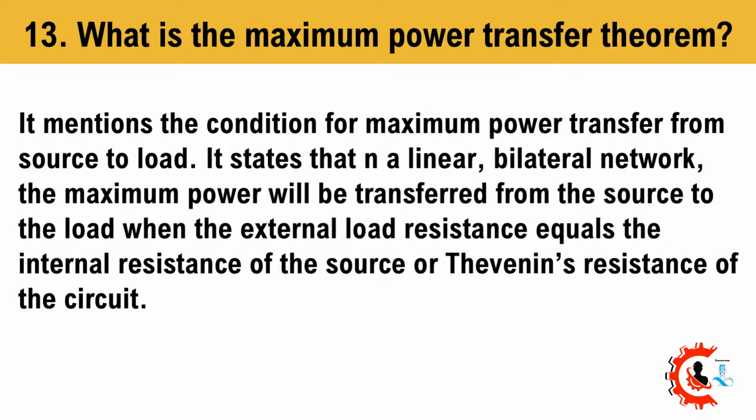13. What is the maximum power transfer theorem? It mentions the condition for maximum power transfer from source to load. It states that in a linear, bilateral network, the maximum power will be transferred from the source to the load when the external load resistance equals the internal resistance of the source or Thevenin's resistance of the circuit.